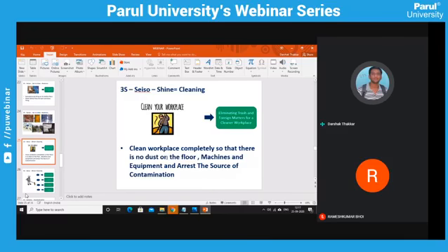So if there is any leakage or any loose point, and there is dust over it which covers these abnormalities, we can't identify them on time, so it may be hazardous in the long run. If we can't identify the small abnormalities, they may become bigger abnormalities, right? So it is most important that we clean our workplace and our machine on a regular basis to identify any abnormalities.